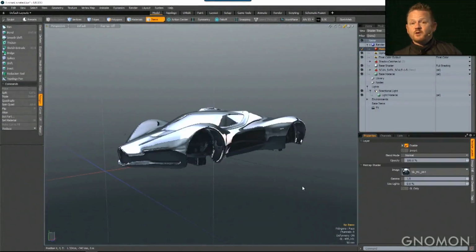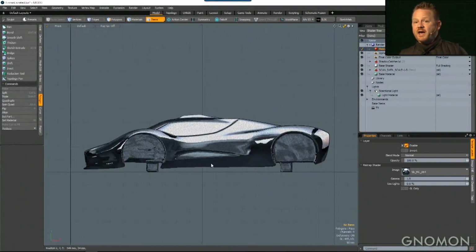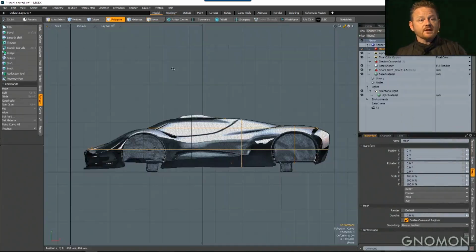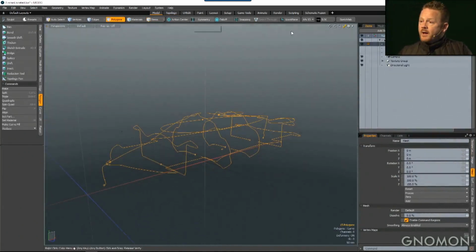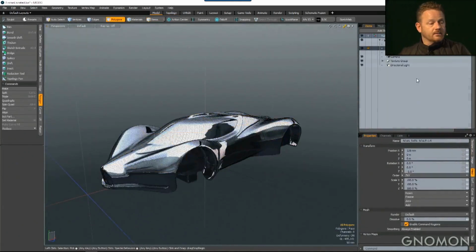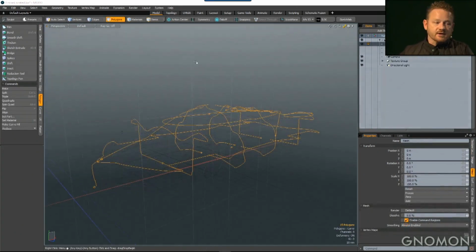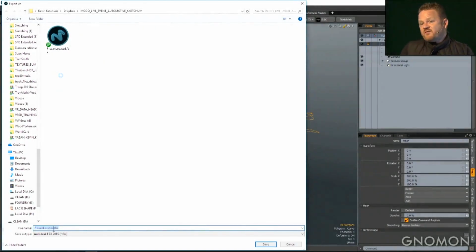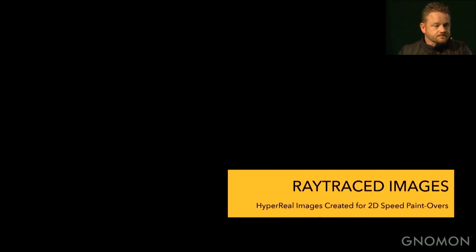But now the designer has been requested, hey, the clay has changed and the engineering package needs to be updated, plus we have new information. So using the contour tool, again, in the retopology tools, I can cut sections at predetermined locations to feed the engineering drawings to keep making sure that we're not impinging or cutting into the occupants. So it's a communication tool, these lines. And then because Modo has FBX output, you can output that into a CAD package and create sections and propagate it and keep the whole engineering community informed.